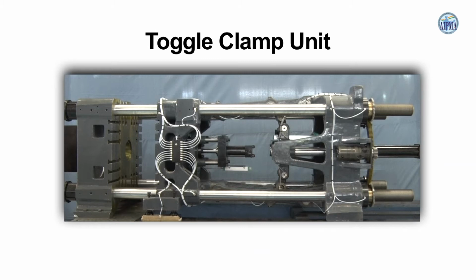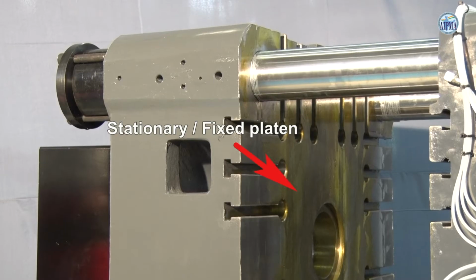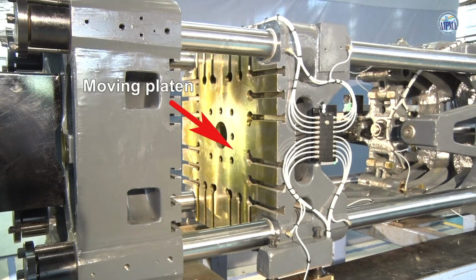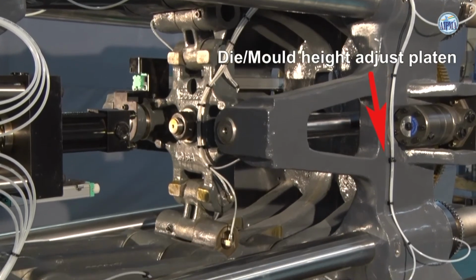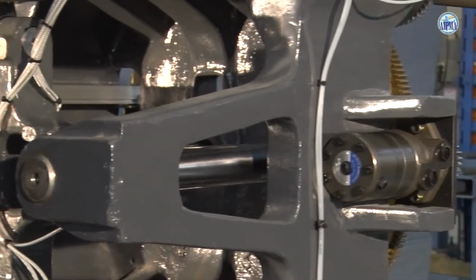Now we are reviewing construction of toggle clamp unit and its components. Stationary or fixed platen. The stationary platen holds one half of the mold. Moving platen. The moving platen provides an area for mounting the other half of the mold. It moves back and forth to open and close the mold. Die or mold height adjust platen. This platen is used to adjust the clamp assembly to accommodate different molds of various thickness and to adjust tonnage.